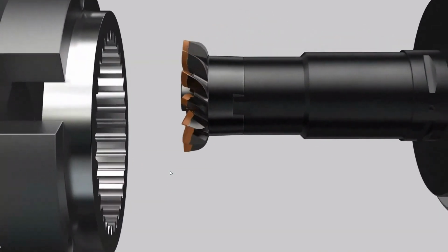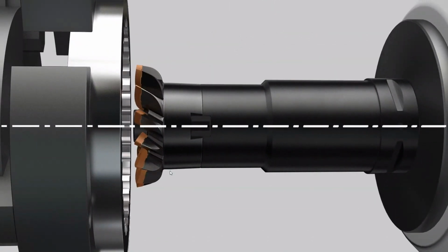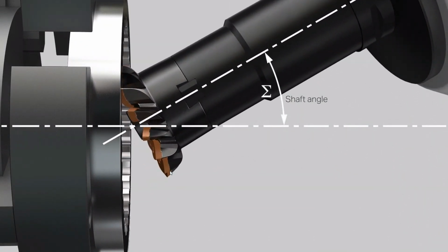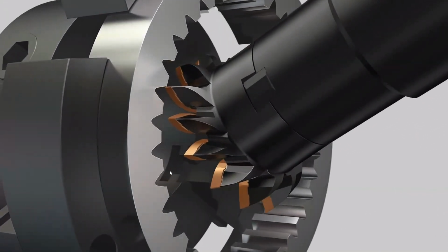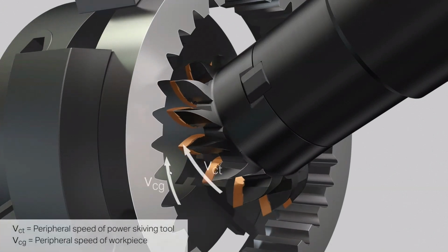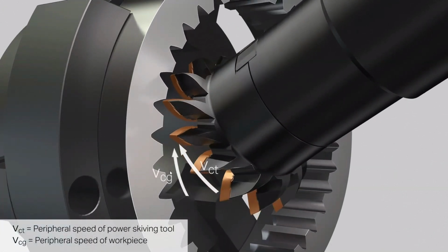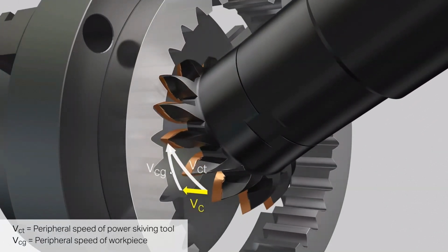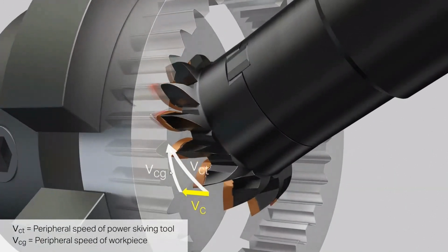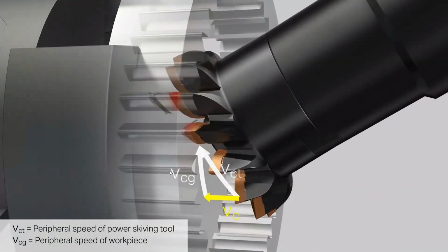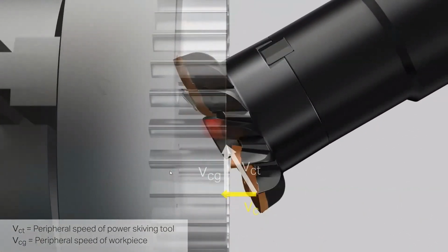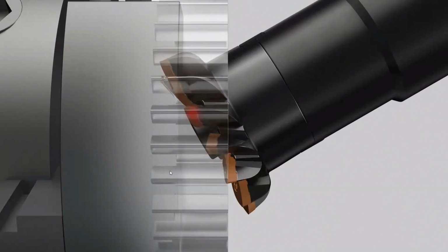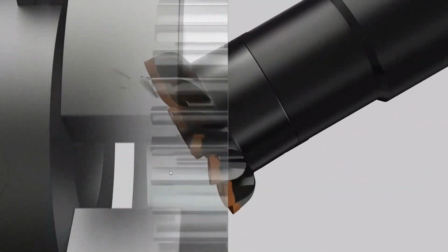So if you imagine this cutter on your B-axis of your multitask machine, and we're doing an ID involute spline on a part, this cutter will be custom built to match your involute spline definition. It'll be tipped at a very specific angle, and it'll be synchronized with the rotation of your main spindle to mill out that involute spline shape. So we have a dedicated team with software and calculators that'll be able to predetermine exactly the size and shape of the cutter that's needed.